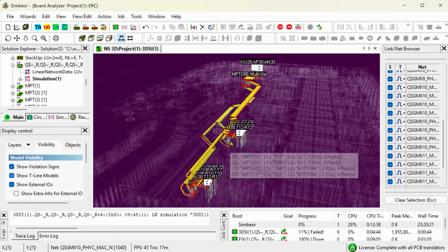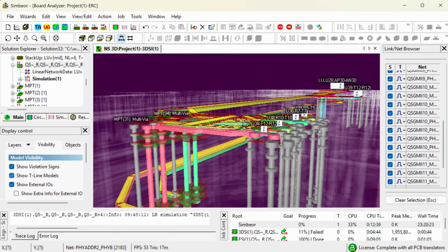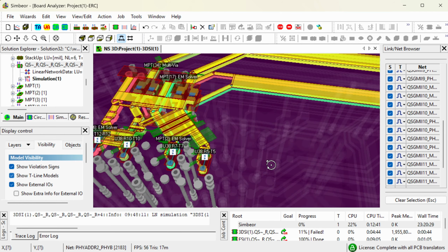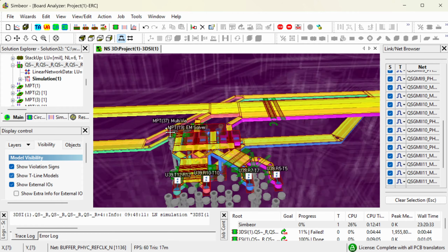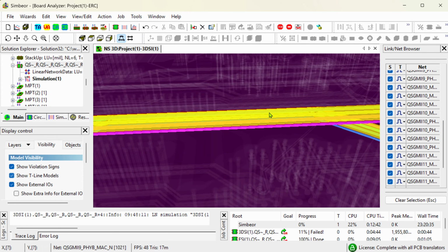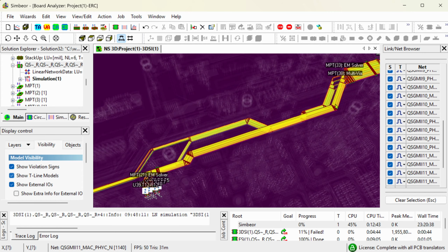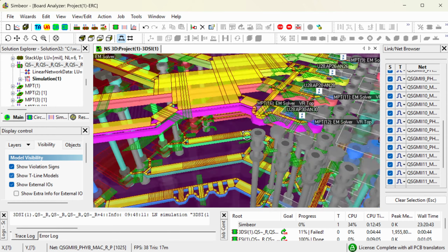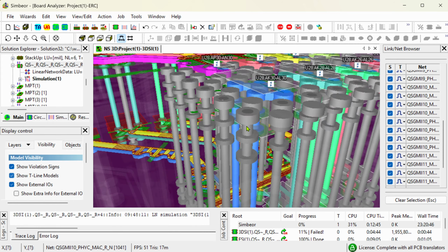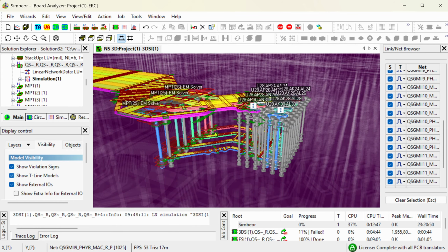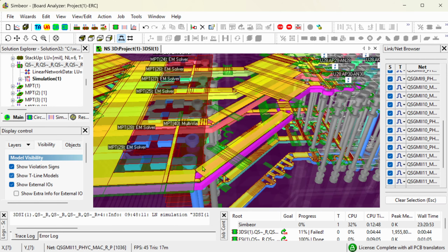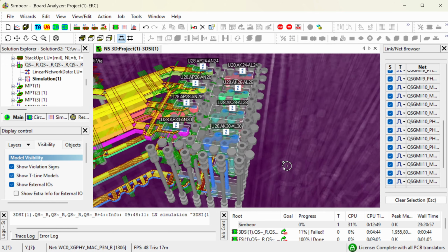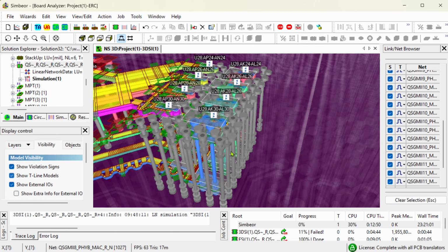So I double clicked. There are some discontinuities here, and coupled transmission line segments all the way. That's where most of this fine crosstalk comes from. And via holes or those BGA breakout areas. Some are identified as multi-vias here, and some are general discontinuities that can be further optimized and so on.